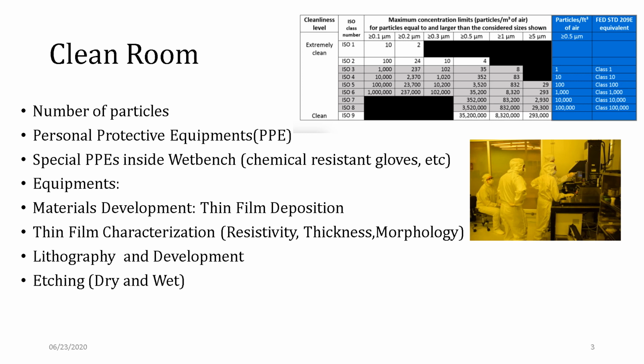So we need to make sure that metals don't diffuse into one of those layers, because when we develop devices like transistors, we will have a number of lithographic layers to be patterned, a number of layers to be developed, and especially the metal layers should not come together to short circuit, so they should not diffuse. So in order to do that, you need to know the resistivity that you're working on before and after a particular deposition, or before and after a particular patterning.